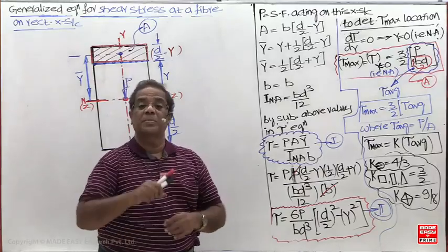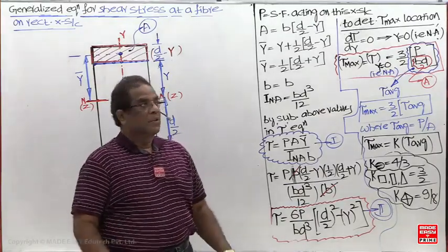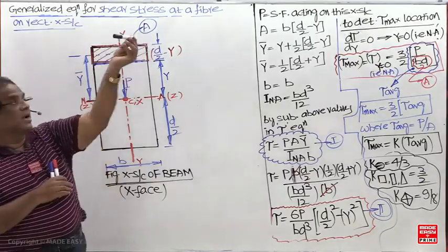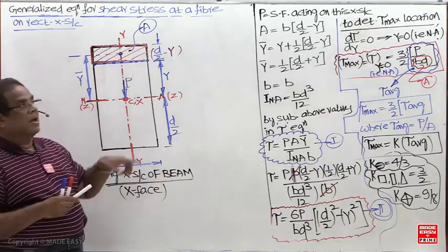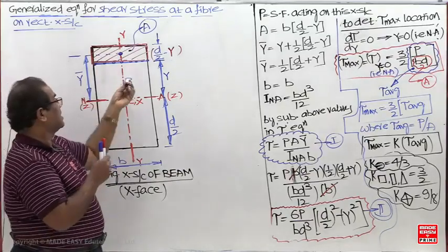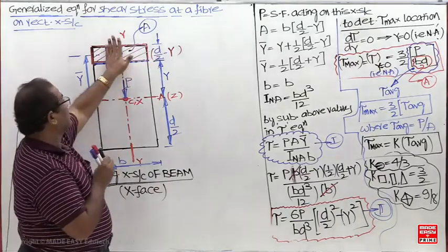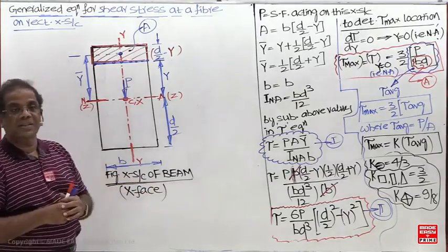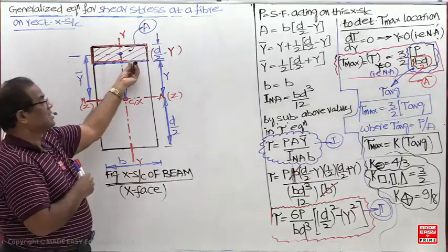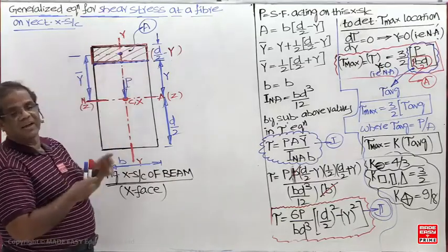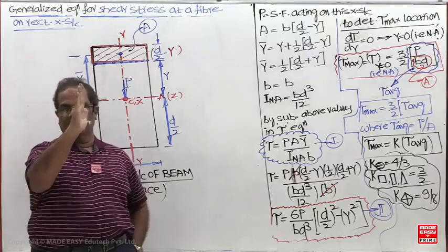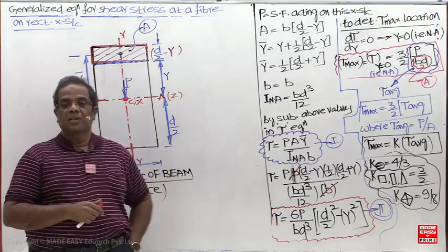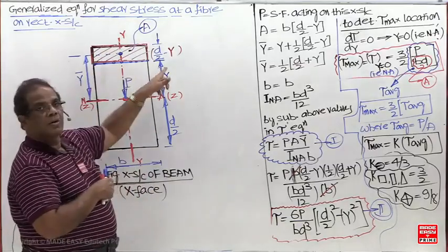So these are the differences between bending and shear stress. Which type of stress is there at the extreme fiber? Only bending stress, only sigma x, a uniaxial state of stress. At the inner fiber, bending stress sigma x and tau xy are both there, which means a biaxial state of stress, so you have to calculate the principal stresses. This is a combined stress.